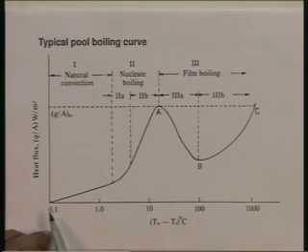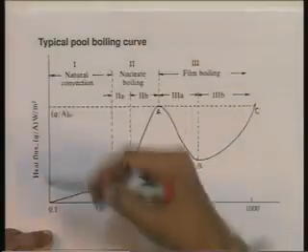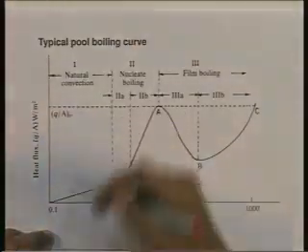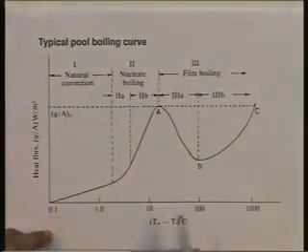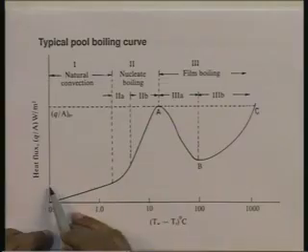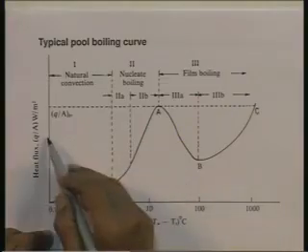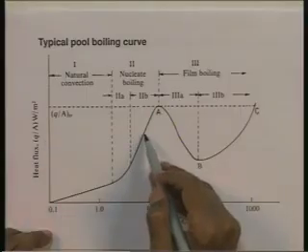All right. So, these are the values of T W minus T S which we are controlling during the experiment. Then on the y axis, we have the values of heat flux, the heat flux that we are supplying for maintaining these values. So, at each steady state, at T W minus T S equal to 1, what is the Q by A? Measure that and put down that value. Next, go to say 10, find a value of Q by A, you get another experimental point.